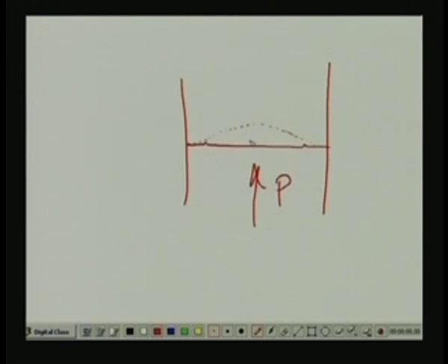Now, you see this interesting thing is that the linearity of the diaphragm depends on how much the displacement is. The less the displacement, the better the linearity we will have. That means pressure versus displacement. So, if I now connect a core of LVDT like this one, primary